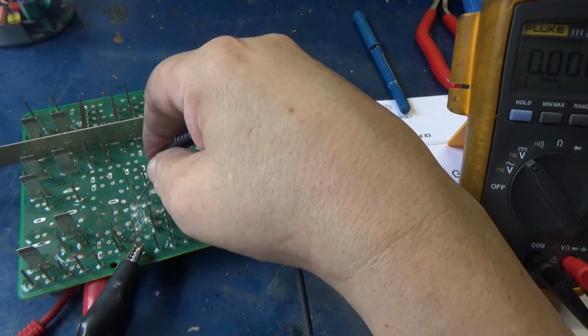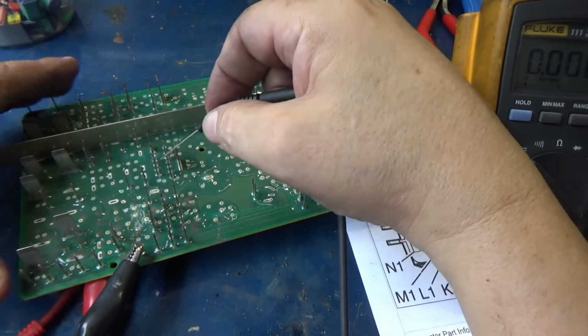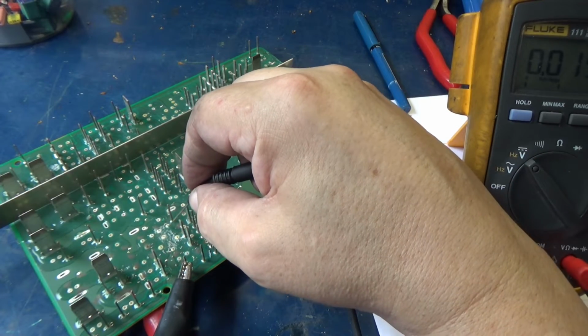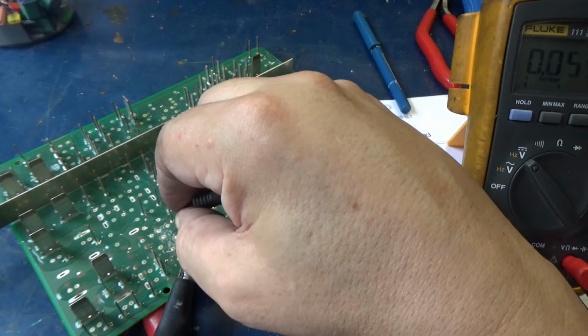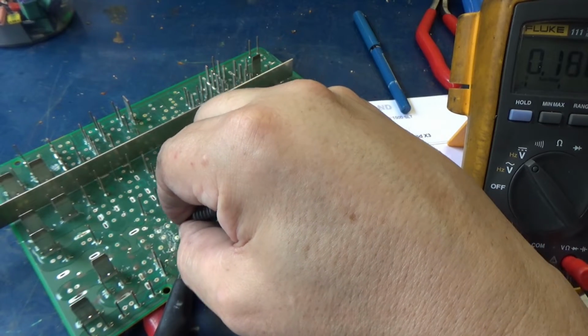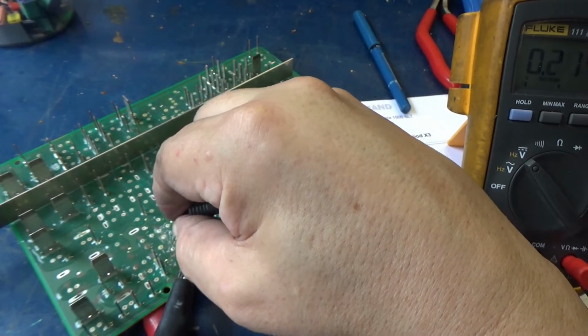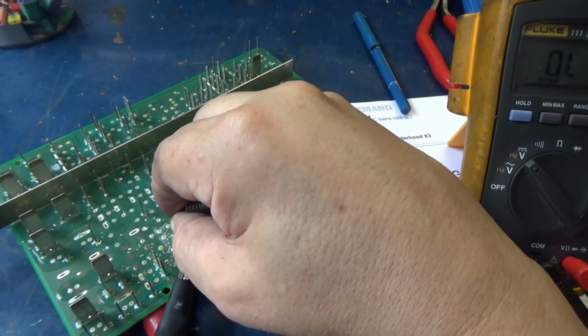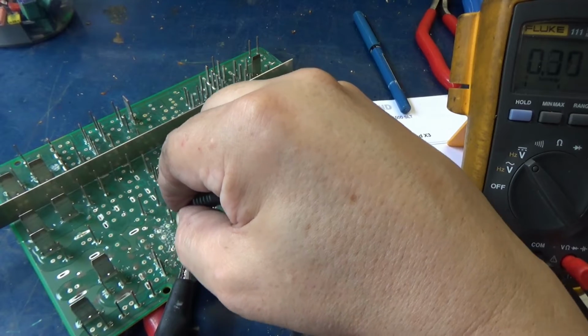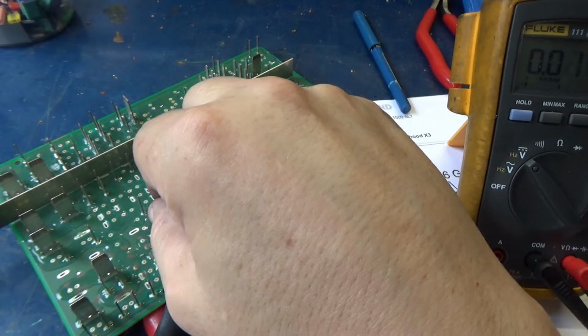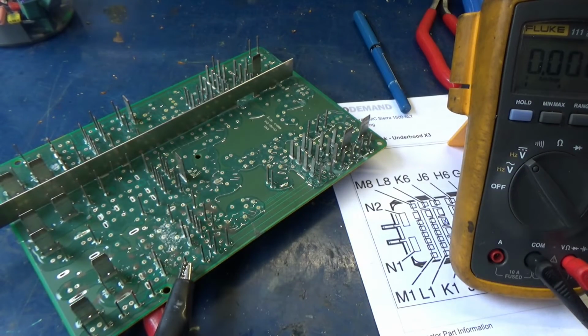I think we've got to unsolder, where are you at here? That one, that one, that one, that one, and that one to get that relay out. There should be 5 contacts. But first you got to get through this protective conforming material. So I'm just going to get me a plastic scraper and start scraping on that, see if I can get that removed.